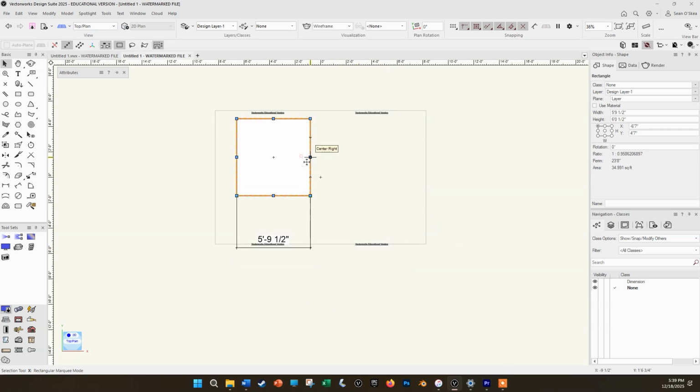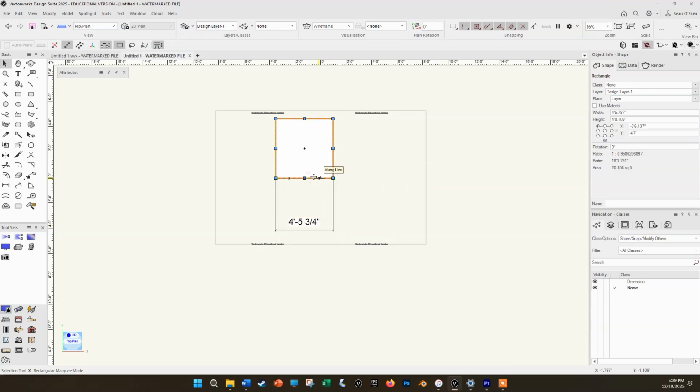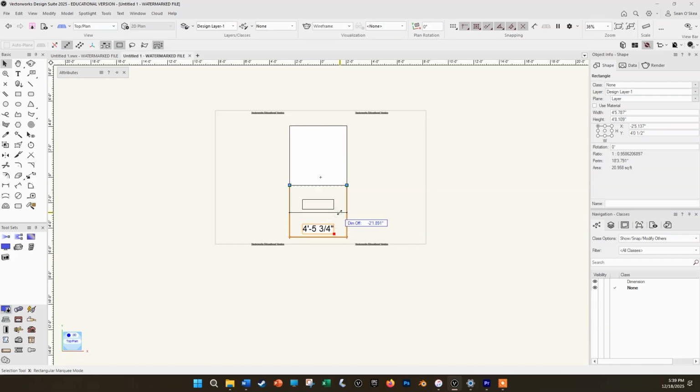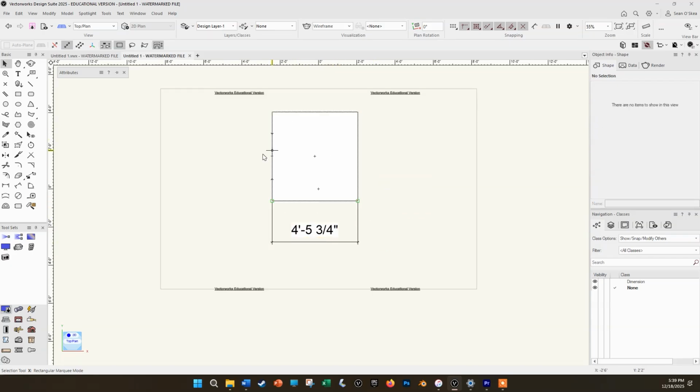And how do you know what's the right scale to use? Basically, it's all about how large is the thing you are drawing and what is the size of your paper. We typically use 1/8, 1/4, 1/2 inch, and 1 inch scaled plates in architecture and entertainment design. But if you want to draw the object as big as you can on the piece of paper, you just want to pick the right size for that. So for example, say you're drawing a hand prop on tabloid 11 by 17 paper, then maybe 3 inch to the foot or even full scale might be fine depending on how big the prop is.